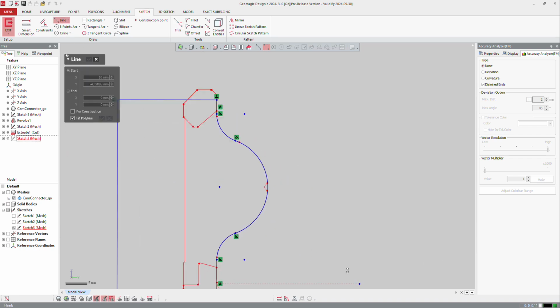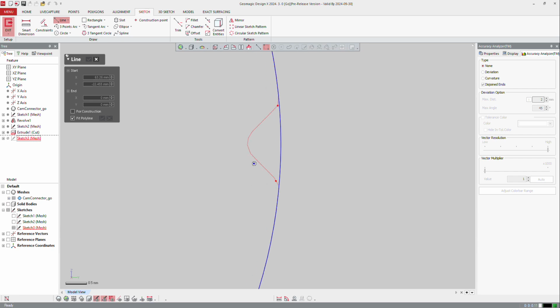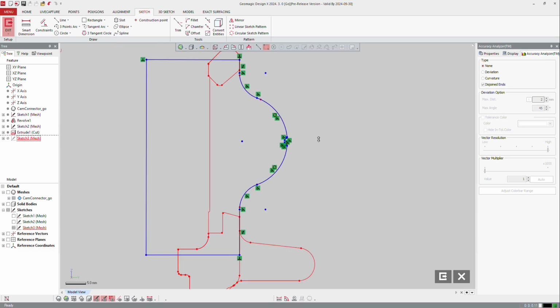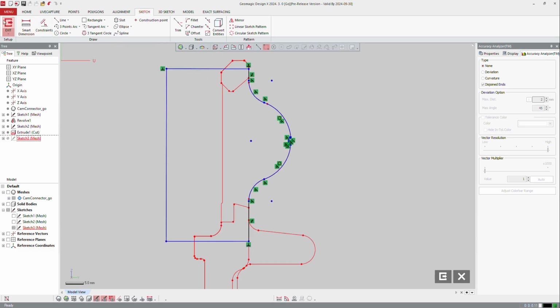And I just need to finish with those little areas. So here and there. Of course, I can trim it. So corner trim here and there, and extend my two lines up to the end. Of course, I can also create the fillet between here and there. And at the end here, if I trim, same thing. So power trim, I will remove that. I can make a small fillet from here to there. You can do that or specify your value if you prefer. Okay, I got the complete definition and I will exit.